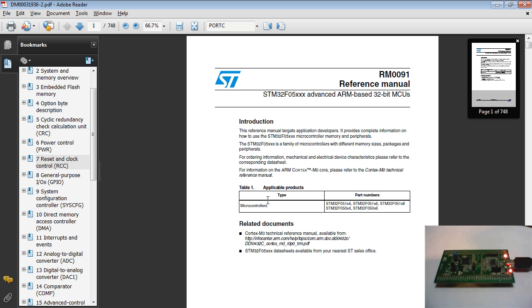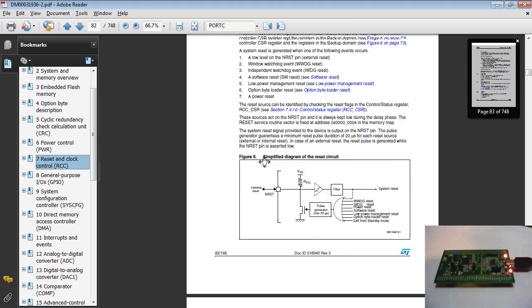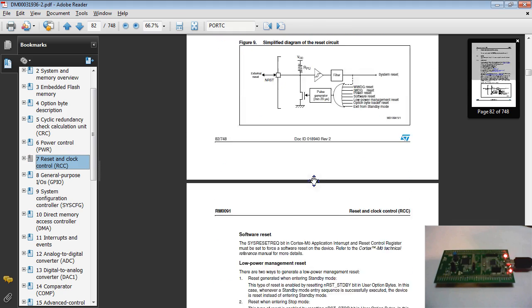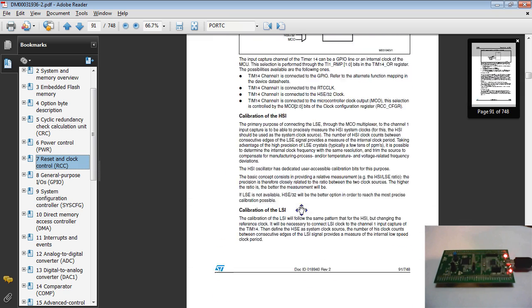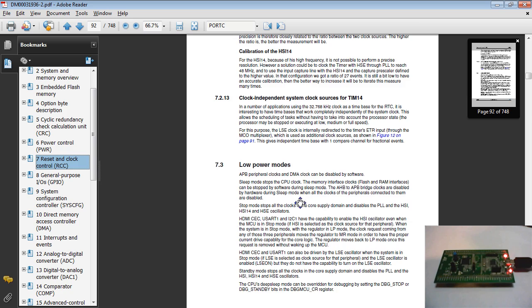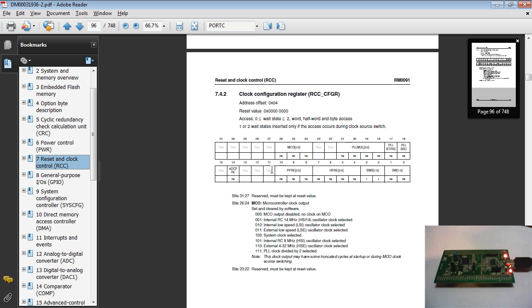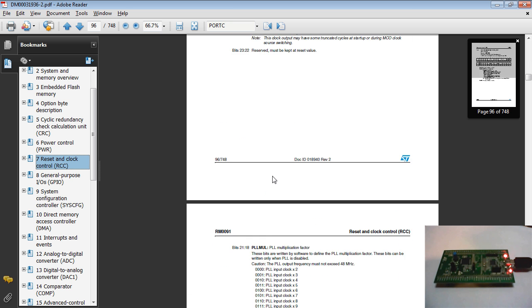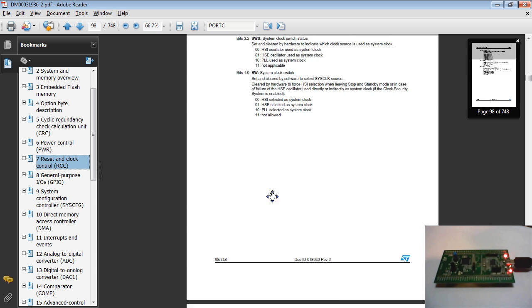in order to blink an LED. Now, ARM processors have some advanced features, such as you can turn off clocks to certain peripherals in order to save power. However, we want to enable those clocks. So there's this reset and clock control register, and one of the registers on here contains information about applying a clock to our port C peripheral.